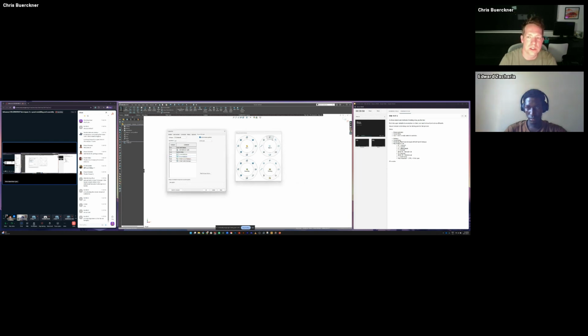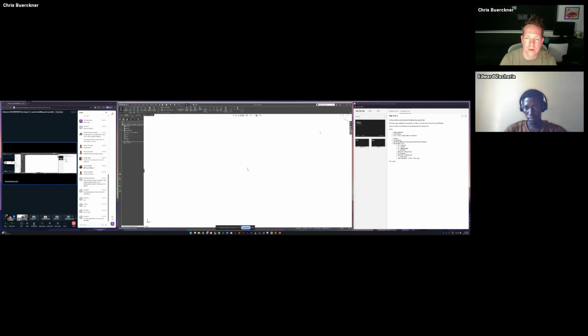All these positions are relative to how you move the mouse. When I'm editing a sketch and want to draw a rectangle, I know I just have to right click and drag my mouse down, and it's going to start a rectangle tool. If I want a line, it's right click and drag to the left, and I have the line tool. Or right click and drag to the right for a circle. These things become second nature as you use them over and over again.